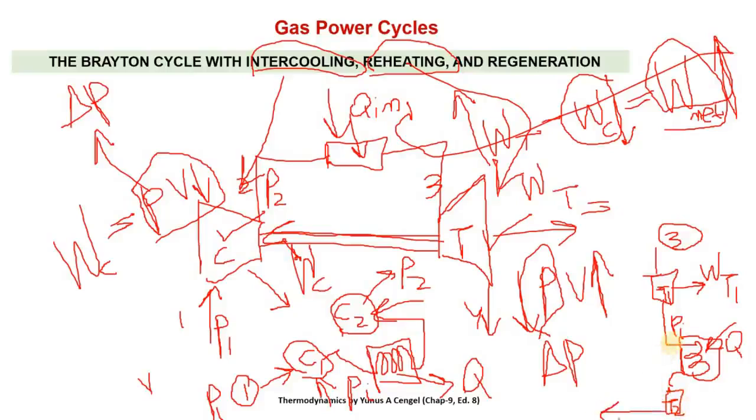And it will reduce its pressure from Pi to P4. Right, so Pi to P4. So now pressure is dropped in two increments, P3 to Pi, then it is reheated, and then it enters the second turbine. So here we will get WT2, and then its pressure drops to P4. So in between we have used reheating.